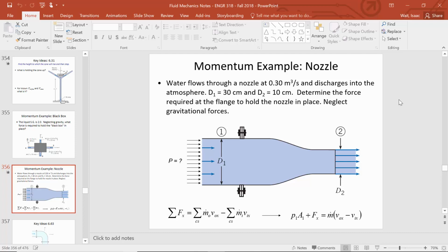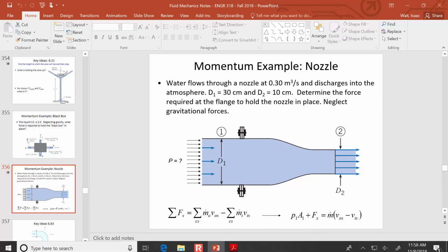And so the water on the outside of that control surface, even though it's not actually a force, it's pressurized water acting over an area, the effect of that P times A is as though it's a force. And so we put external forces on the left side, and then what's left over, this F of x, is, after you account for the external forces, what force is required to hold the system steady.